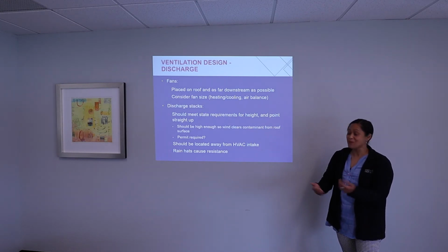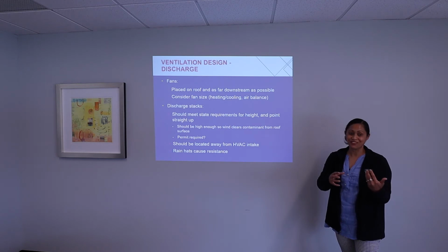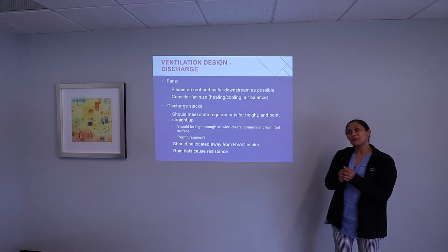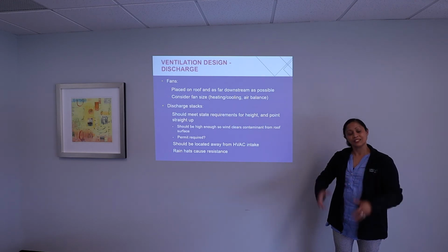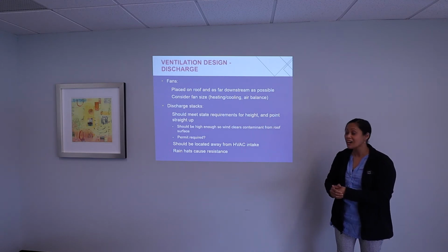And another important thing to note is to make sure that the discharge stack is located away from the HVAC intake, right? You don't want it coming back in. And also, I think sometimes in the design of the discharge stack, they try to put something to protect it from the rain, protect it from coming in.